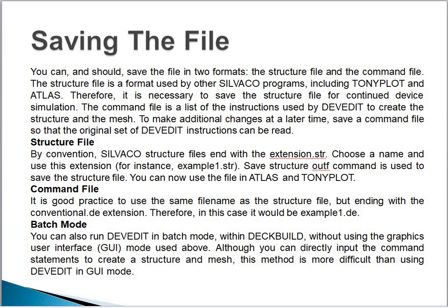example1.de. Batch mode. You can also run DevEdit in batch mode within DeckBuild without using the graphical user interface mode used above. Although you can directly input the command statements to create a structure and mesh, this method is more difficult than using DevEdit in graphical user interface mode. Using DevEdit in batch mode, you cannot call the structure by using the Atlas command. So we are using the graphical user interface mode to call the structure in the Atlas command.